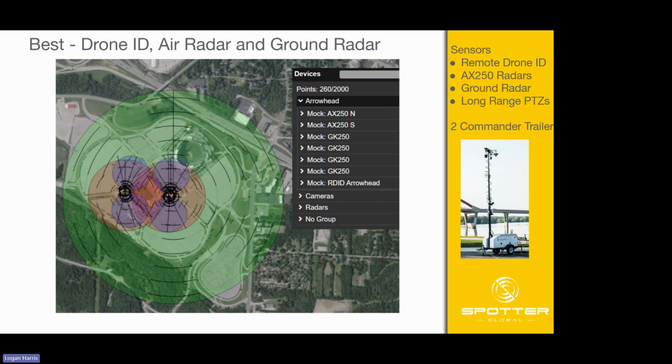Also on the radar system side, that also takes calibration, because you have to make sure it lines up with the angle position. We can build these with GPS, which helps it register faster, but there is some calibration that has to be done to dial it in so it lines up with the camera system.